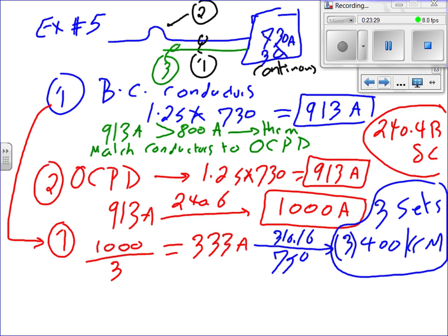Like for example, I have a 15 amp circuit breaker. Can I put number 12 on a 15 amp circuit breaker? No problem. Bring it on. That's the same scenario. I have number 12 conductor tied to a number 15 circuit breaker. Is it okay? Yes. So I have an 800 amp circuit breaker tied to a 900 amp conductor. That's okay. So that's another scenario.